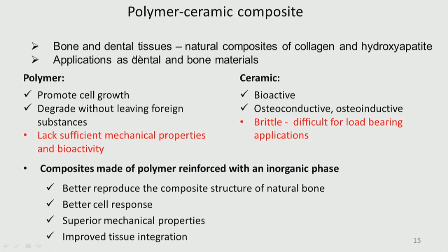So, by adding this, you can see the advantages of both are taken in. The ceramic could be bioactive, osteoconductive, osteoinductive. Polymers do not have that property, but polymers can promote cell growth, they can also degrade without leaving any foreign substance over a long period of time. So, we can nicely use them for tissue engineering purposes, growth purposes.